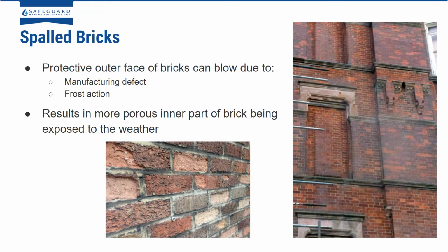Spalling of bricks can be quite common in terms of the porous materials, where the protective outer face of the bricks can blow due to either a manufacturing defect or frost action, so freeze thaw. And what happens is this results in the more porous inner part of the brick being exposed to the weather, and so it will actually absorb more moisture when it starts to spall.